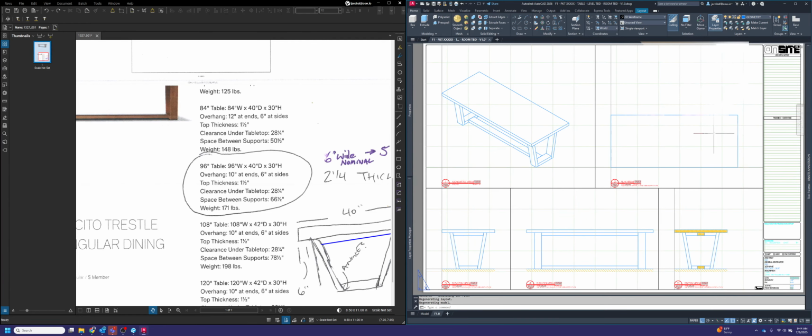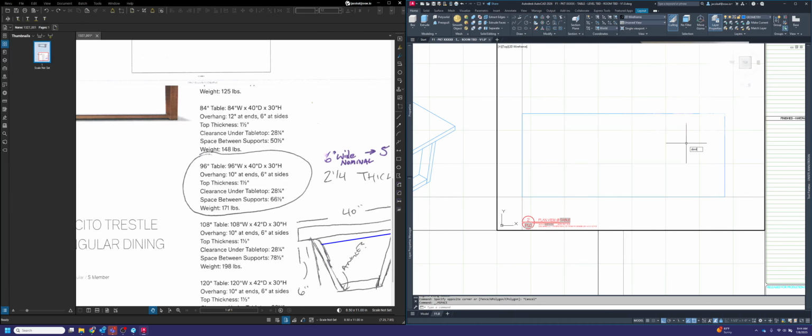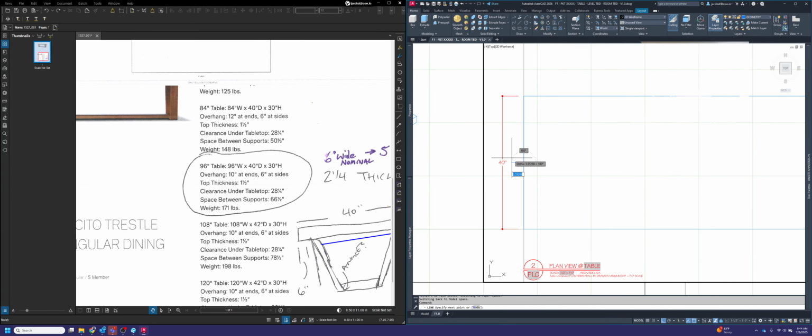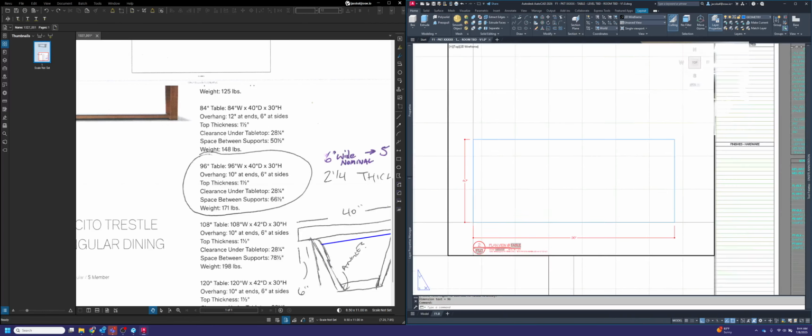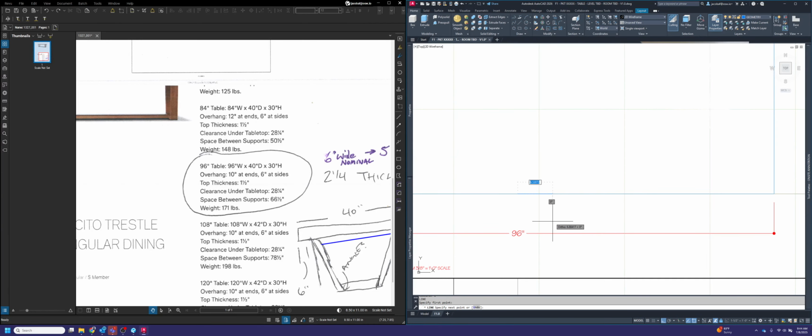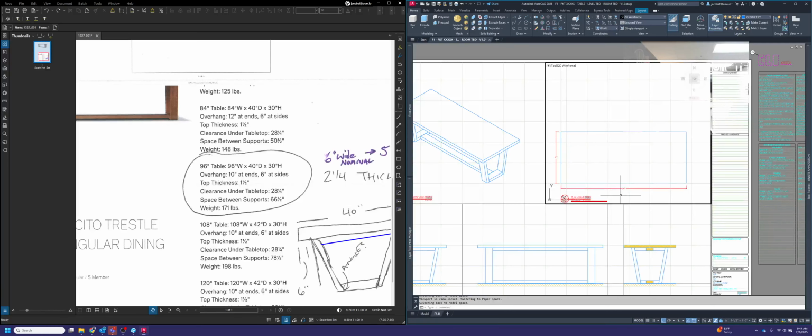So, all right, let's start dimensioning everything. So tabletop, let's go here. We'll go 40 inches for that dimension. And what I like to do, again, just to not beat a dead horse, but I definitely like to make sure that all my dimensions are pulled off my view at the exact same offset. So I'm going 4 inches here off my view, drawing a line 4 inches down off my view, snapping my dimension to that 4 inches, and then deleting it.